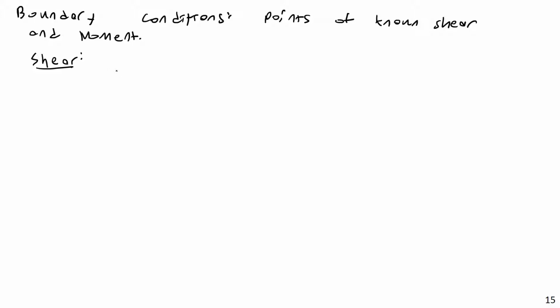Basically, one thing to keep in mind is that at the start of a beam, let's say you have a beam like this, and you solved for the reactions and found that this is 10 kips here and 5 kips here. Immediately, I know, whatever the arbitrary load function is doing between these 2 points, that with reactions of 10 and 5, on the left-hand side of the beam the shear is going to jump up to 10. Basically, point loads cause jumps in the shear diagram, which means I'm going to be at 10 here, and then I'm going to be down at negative 5 here. This is the v as a function of x.